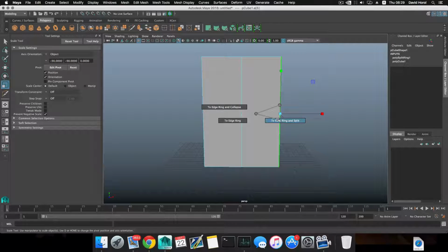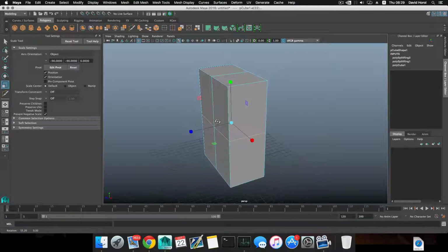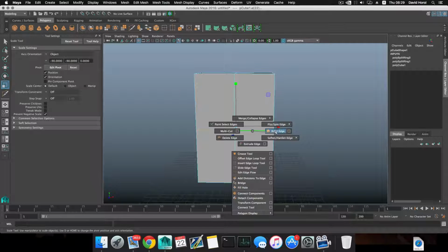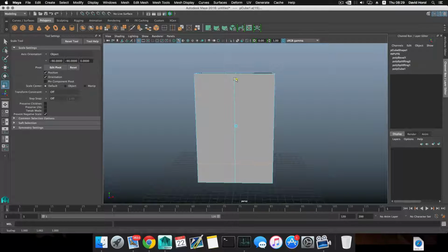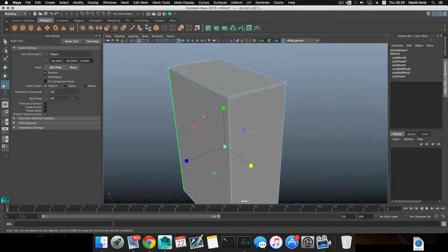By the way, because this is a box, I'm almost certain that you can always tune the size, the scale of this, but you will need to do this properly. Anyway, I'm creating those extra edge loops in the center, and then bevel each one of them just to create a frame on top of this box. So beveling it and using the scale tool to scale this. I'm going to bevel this one as well. Double click on this one, shift double click on this one, scale it to the sides, just to have a frame whose purpose is to contain everything that will be inserted inside.